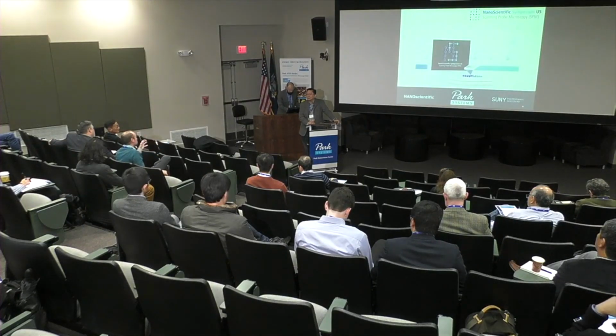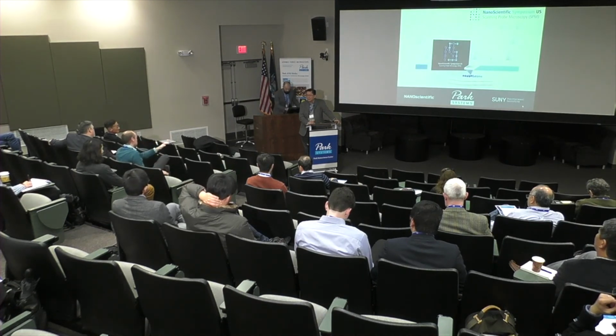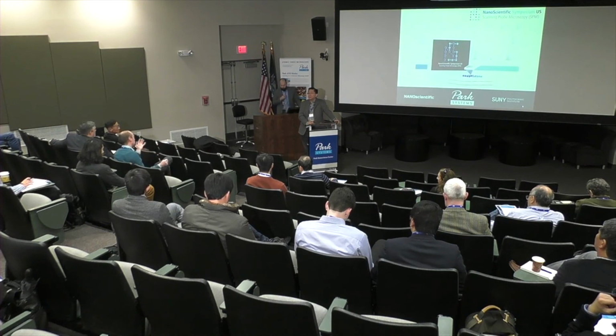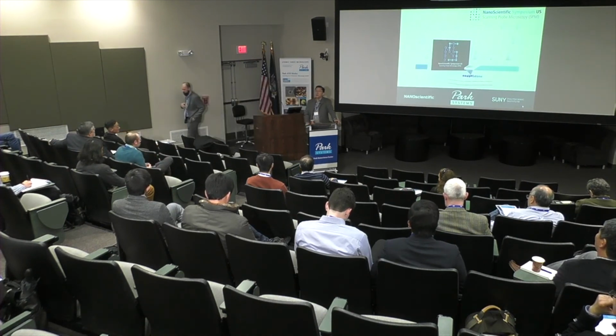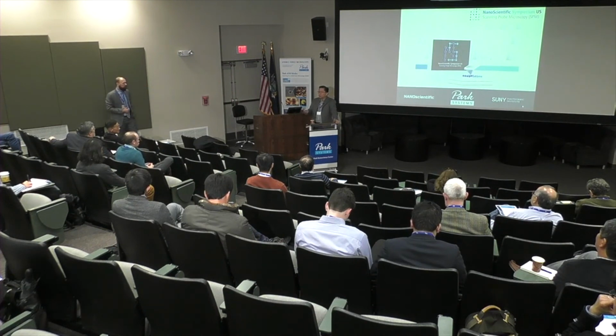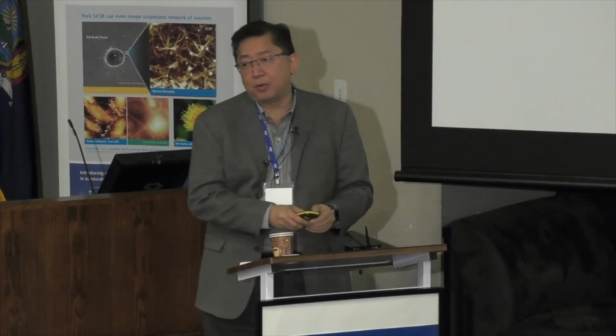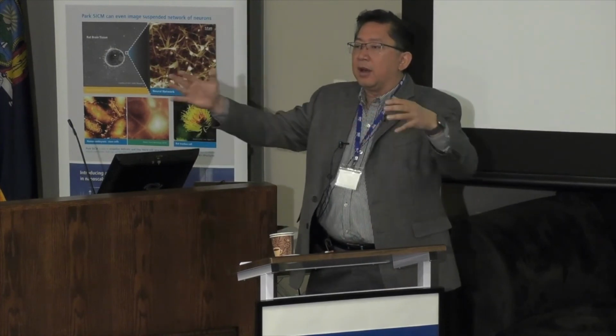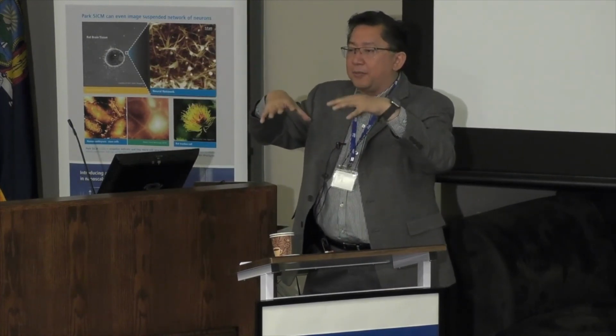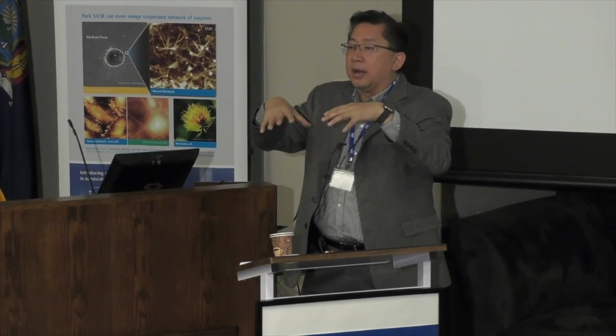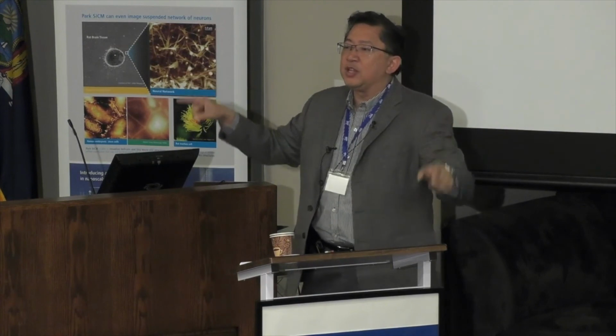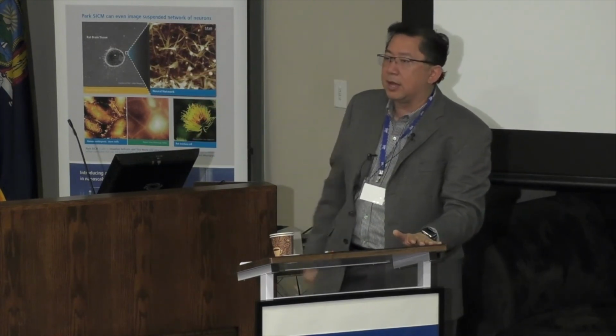I assume there's a reason for designing material like that, but maybe I didn't pick up on it. I see the sort of self-cleaning window stuff and so on. Correct. So the inspiration there is basically self-cleaning windows or smart surfaces that are stimuli responsive. So the main phenomena there is the Cassie-Baxter approach. But basically what you have is this hierarchy of roughness, and you have, during wetting, a lot of air trapped inside that cannot go or move somewhere. And then you have the surface tension defined by the tip of those protrusions.